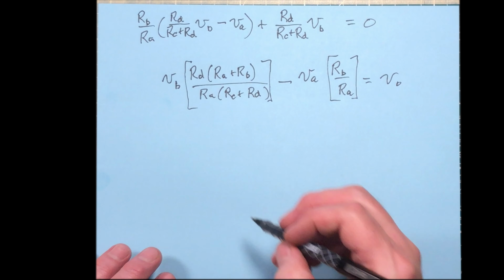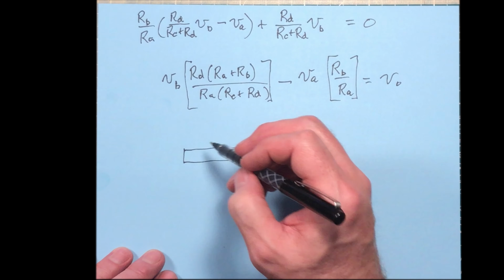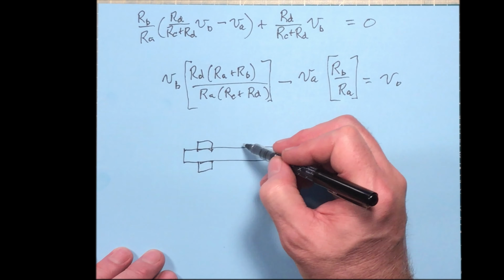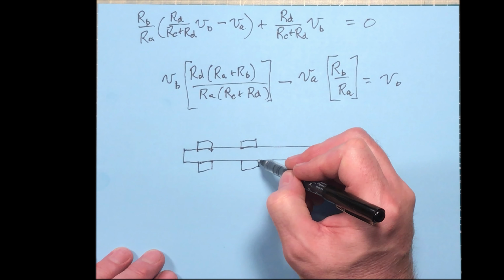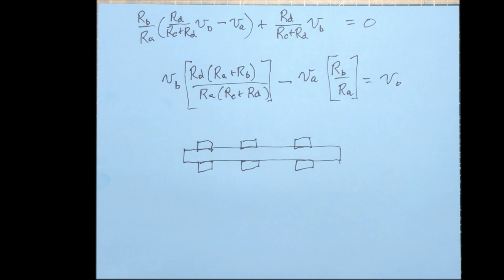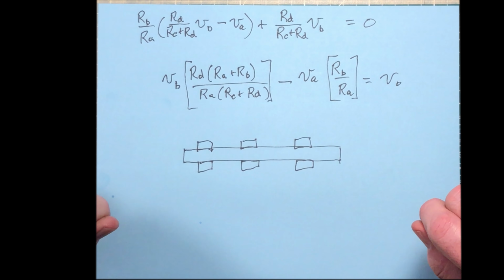But the basic idea is that you've got some kind of, let's say, a metal bar here. And you place gauges on either side, one there, and these are welded or glued very firmly to the bar here. And you set them up in pairs. They contain a device that has a resistance that changes when it's placed under stress. An example of that might be something like a nichrome wire. If you take a nichrome wire and you stretch it like this, you put it under stress, its resistance changes. And you can also compress it and its resistance changes as well.